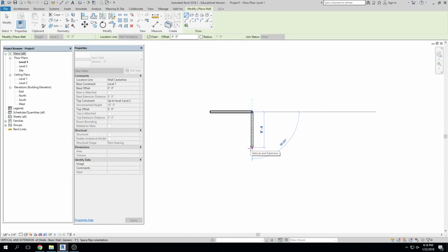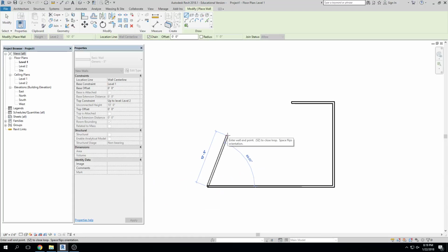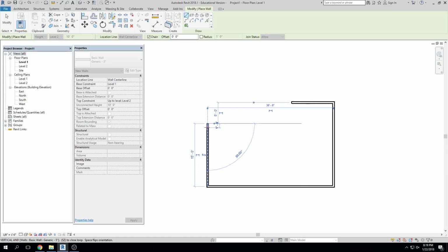Let's do a 20-foot wall in, we'll call this the southern direction. So we want it to be straight, 20 foot, enter, right? Let's go this direction. Let's do 30 foot. We have to pan over a little, and then we'll go up this direction. North, we'll do 15 foot, or I don't even need to do, sorry. See, old habits, right? 15, enter.